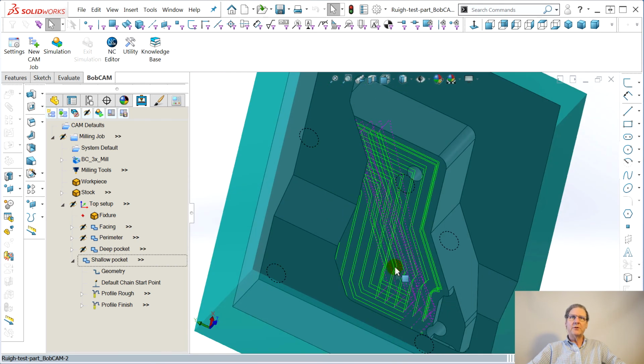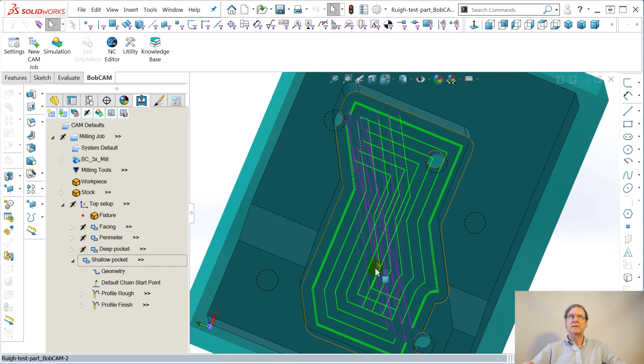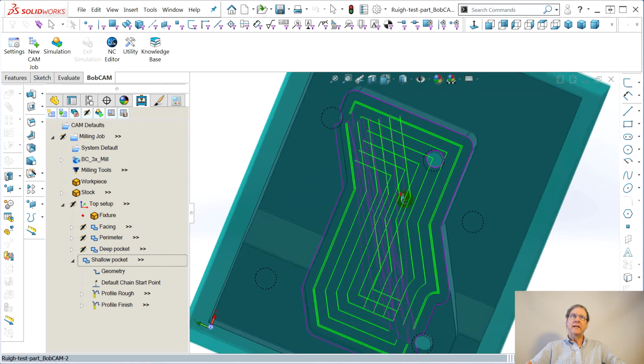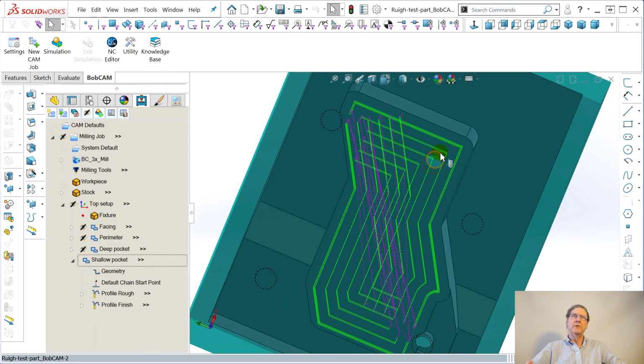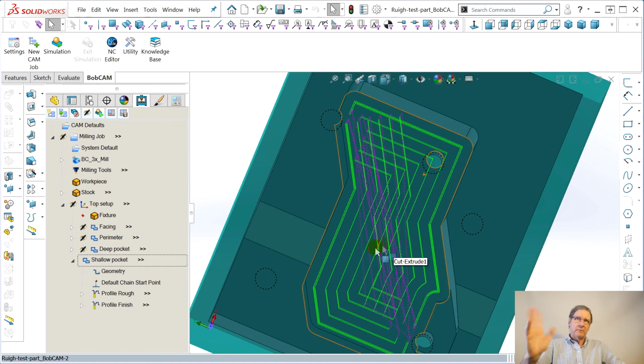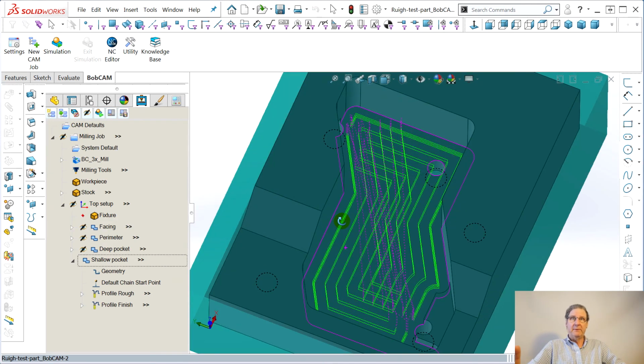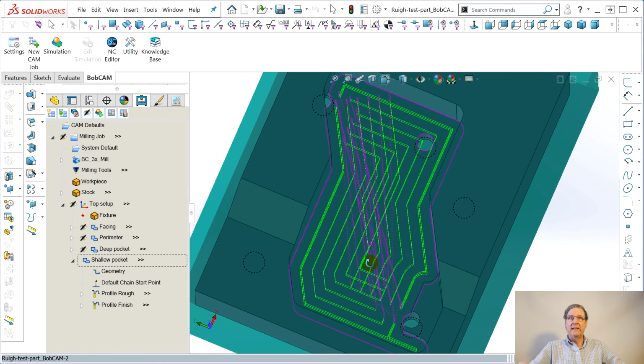And you always watch real close. All these purple lines, because those are traverses, and if you got a post sticking up somewhere, you know. One interesting thing is when it selected the face, it knew enough. Some programs want to cut this out. It'll look at the face and see that there's a hole here, and it'll leave a post right here sticking up because you didn't say to cut it. BobCAD, maybe it's a bad feature, maybe it's a good. It just happened to act the way I needed it to act.